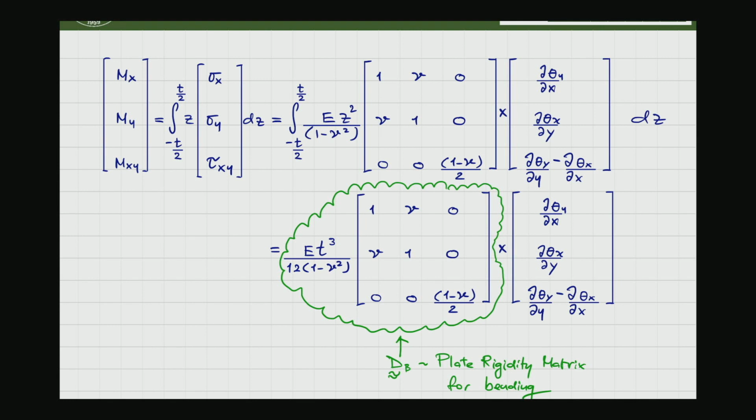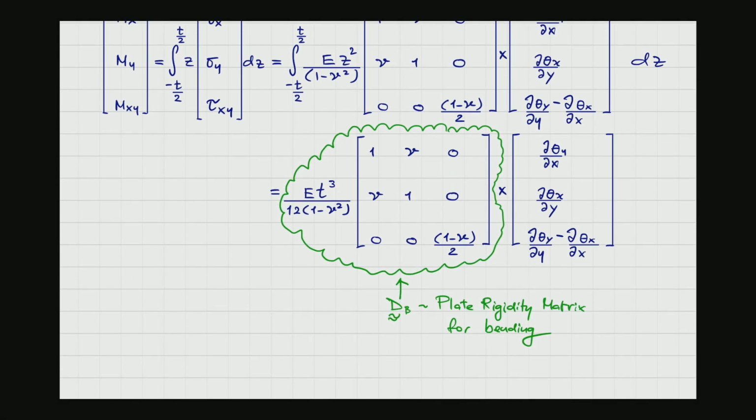The thing is, okay, you have the rigidity matrix. This part on the back here is producing something which is pretty much like curvature. This is the derivative of rotation with respect to x. So rotation change, the rate of change of rotation with respect to the x and y coordinates, that implies the curvature. Alright.